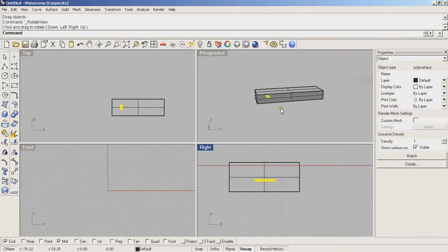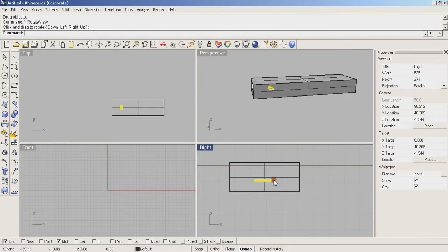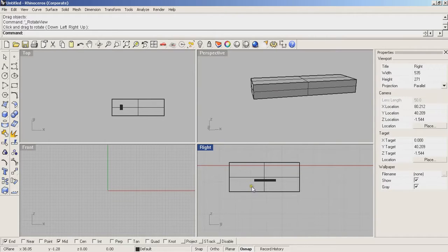So the airfoil is inside, let's say, the duct where we are going to make the CFD animation, and the airfoil is the boundary layer, so we will have to subtract it from the air duct, and we're gonna do that on Workbench because we can't do it over here.